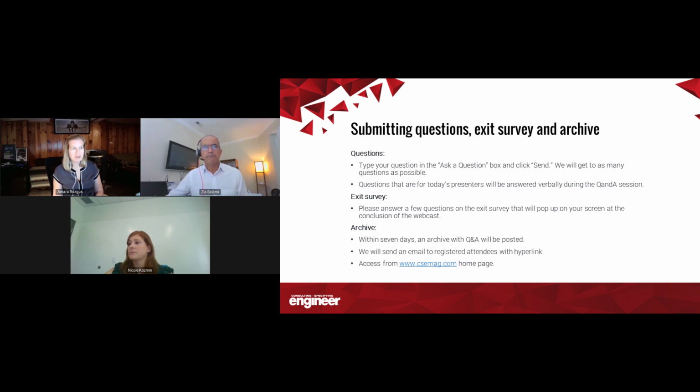Nicole, another question for you. Can you please give some info about grounding of equipment? Sure. Generally, your UPS system is recommended to be ungrounded. But having said that, I have run into instances where different manufacturers have different grounding requirements. So it's important to follow what they recommend, because they are monitoring ground faults on their system and they may have different grounding requirements.